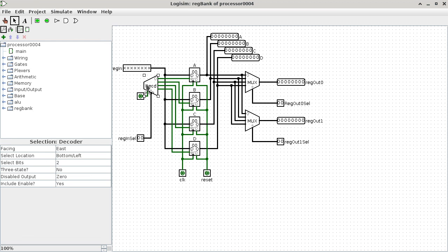It does not have an input. That is correct. It doesn't have an input because the input is implied to be a single bit of 1. In other words, a decoder is basically a demultiplexer with a constant 1 as its single bit input. That's it. It's just a special case of a demultiplexer.